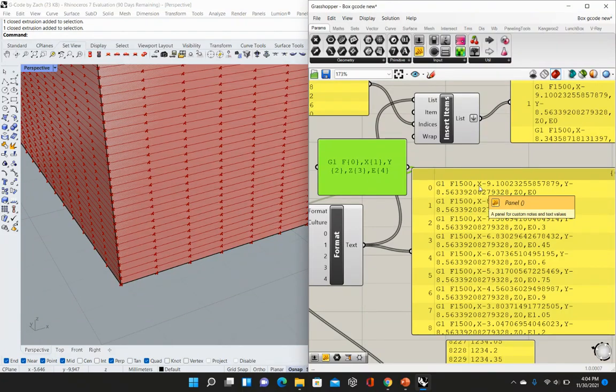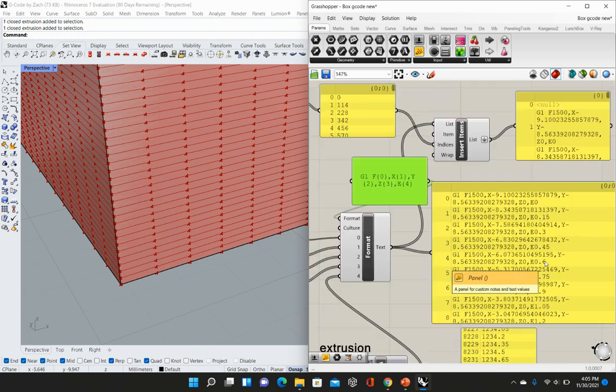And it's telling it to move to these coordinates, which is the culmination of all the points that we've brought together in this formatting text. And it's telling it to extrude nothing because obviously we don't want it to extrude before it hits the first point. But as soon as it hits the first point, we're telling it to extrude 0.15 millimeters of material, which we get going because you need material to come out each time.